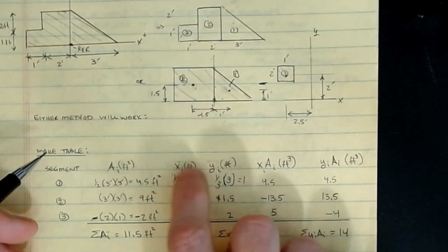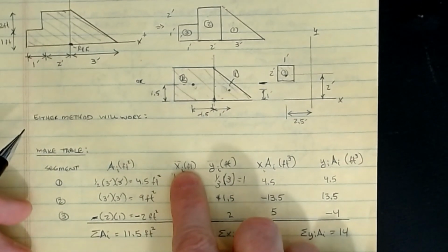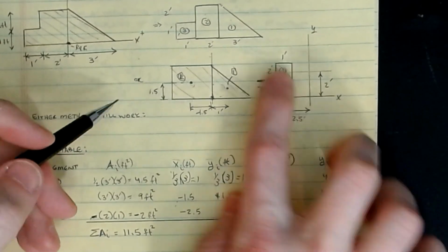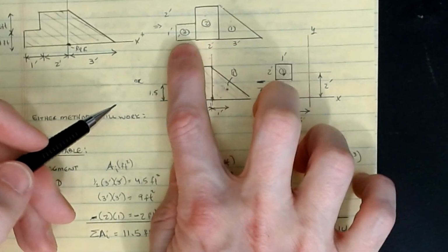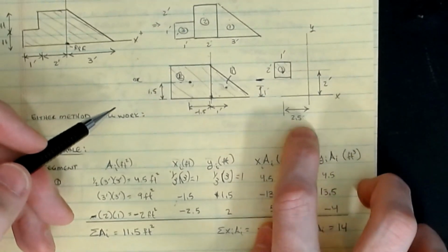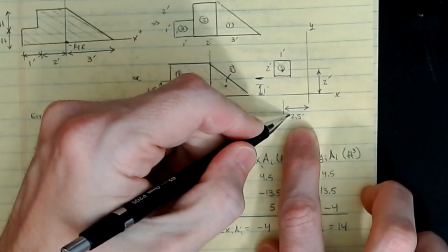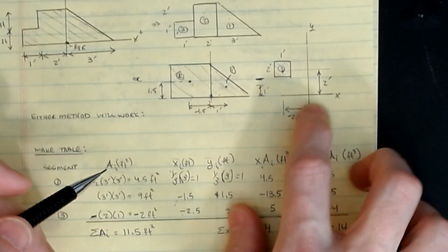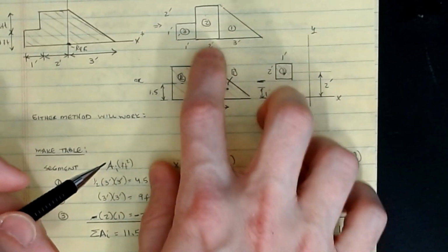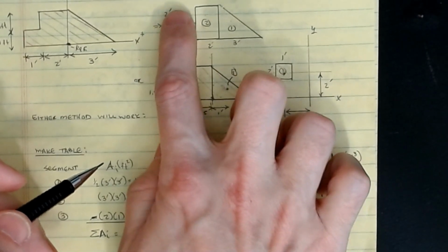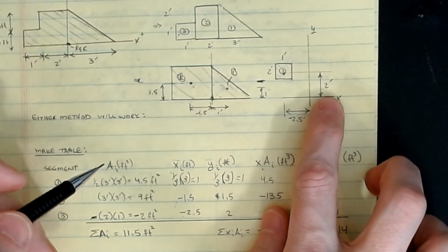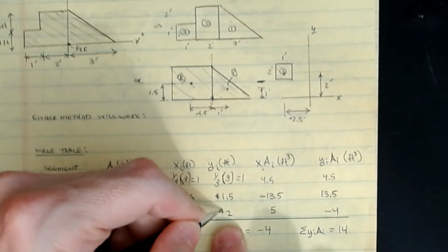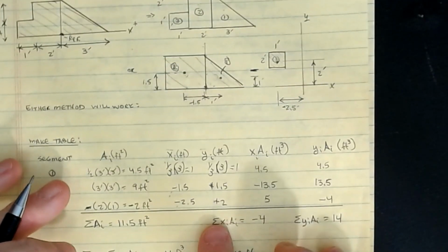And so then the centroid, where's the center of this located? Well, we're measuring relative to this point. To get to the center of that rectangle, I go over 2 feet and then over half of 1, so my total distance is minus 2.5. So it went in as a minus 2.5 here. To get up to the center, I go up 1 and then plus half of 2, which gets me a total of 2 feet up. That's where the positive 2 comes from, because we're going in the positive y direction. Okay, so far so good?